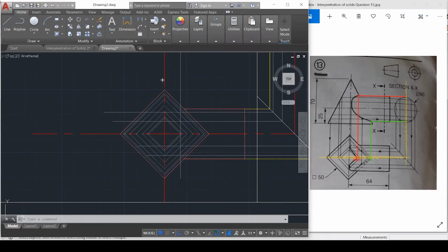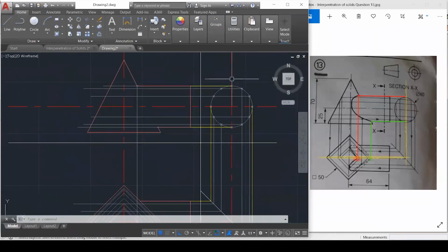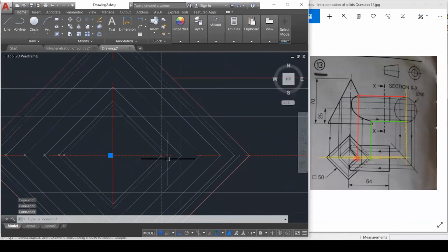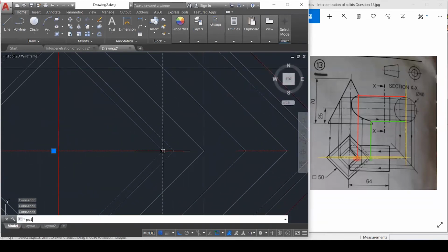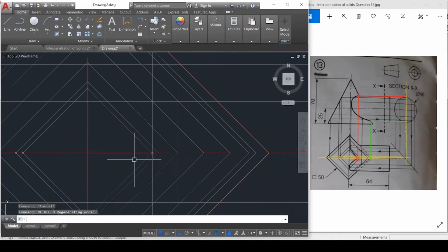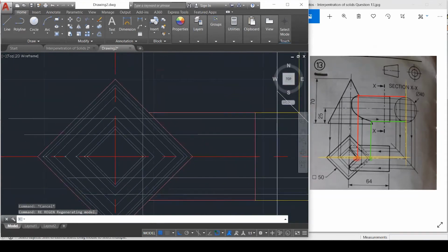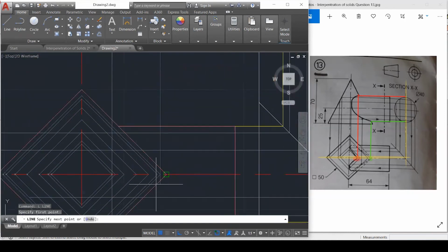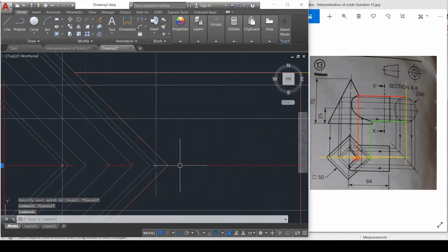So let's now go back to the AutoCAD drawing and see if we can locate these points now that I've just set that up. So start here at the top, go across, it's my top point, and let me go down, and my top point intersects my center line right here. So where that intersection is, that's my point 1, or what I will say, that's my highest point, which is in the red. Now let's look for the lowest point. So we can project from this lowest point down here until it touches the red line. Right, so they intersect right here. That's the lowest point.